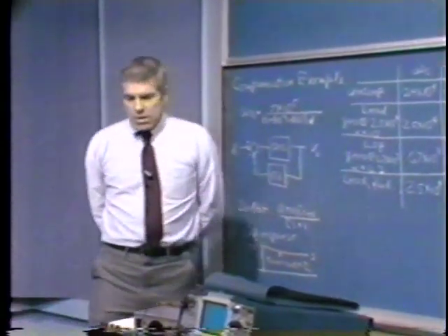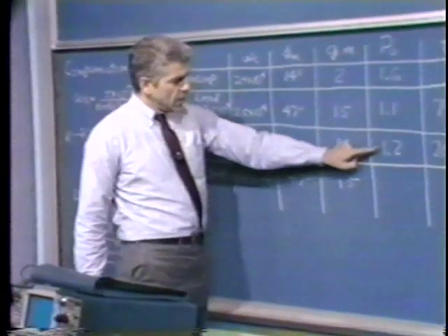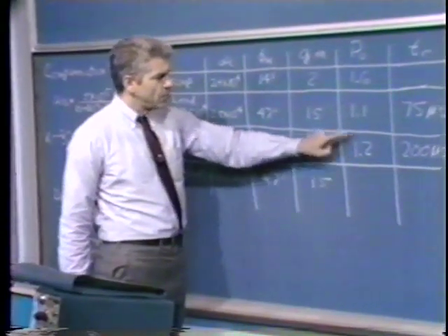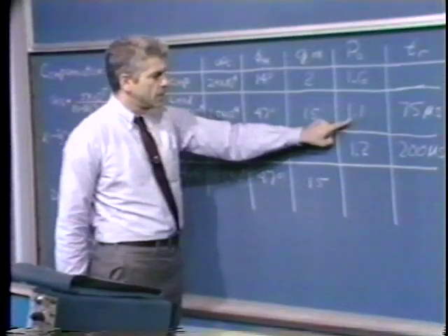Well, there's one apparent discrepancy that I'd like to spend just a little bit of time talking about. We had said that for systems with corresponding amounts of phase margin, the speed of response should scale just about directly with the crossover frequency. Furthermore, there should be a very nearly one-to-one correspondence between phase margin and any other measures of relative stability. The unfortunate part here is that we find out that in the lag compensated system, we get a little bit more overshoot than we do with the lead compensated system.